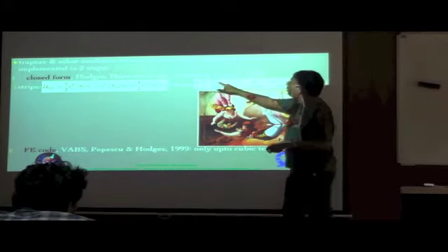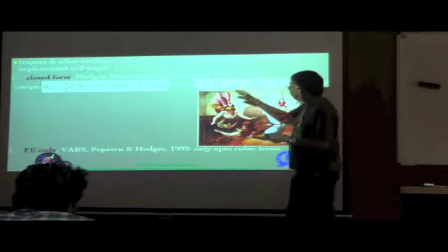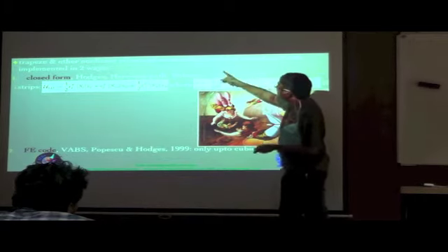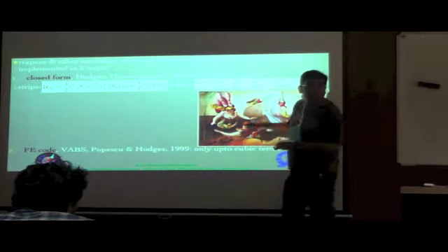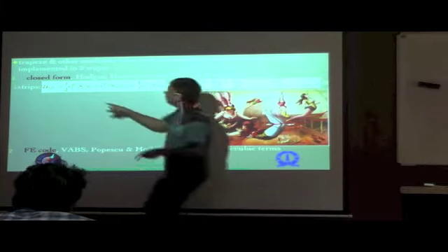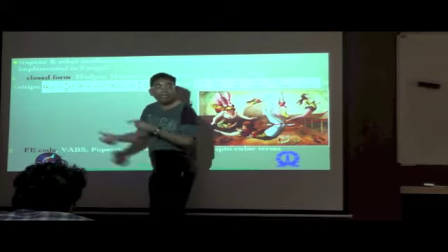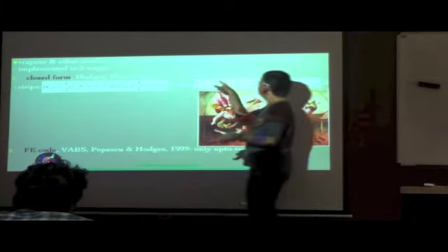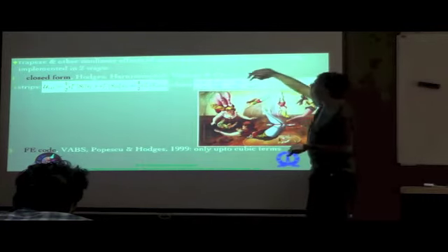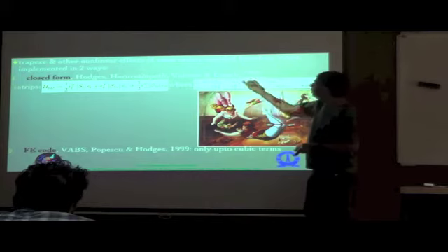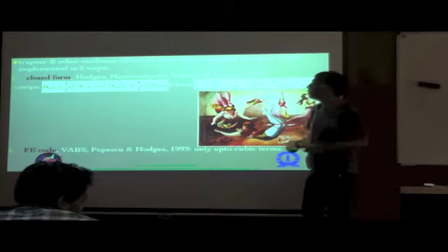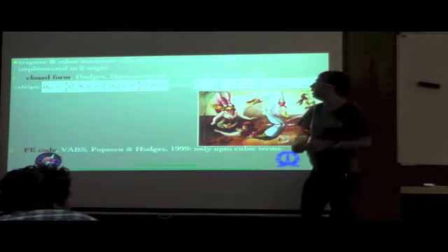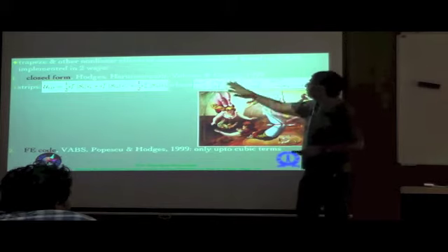The second time, the axial force, the bending moment, the torque and the two bending moments. The second time you take a derivative with respect to each one of these, not only like dou squared u1t divided by dou gamma 11 squared, but also combinations dou squared u1t by dou gamma 11 dou kappa 1, etc., then you can populate that particular matrix SL in an equivalent form. You will see that those terms become functions of gamma 11, kappa 1, kappa 2, kappa 3, in particular kappa 1 and kappa 2 more, because they are the large quantities as far as strips are concerned, because it is torsionally soft. At the same time, it is also soft in bending in one of these directions. So these are the two large quantities in this vector.